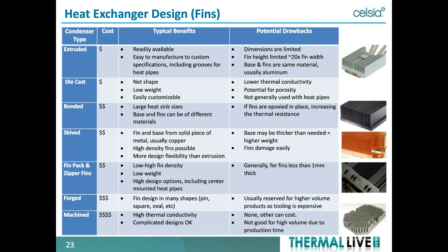The heat exchanger design used for these devices is no different than what's used in just typical heat sinks. You can use extruded heat sinks, die-cast heat sinks. You can use bonded fin, skived fin, fin packs, forged fins, machined heat sinks. I think the most common that are used in the marketplace is probably fin packs because they're used in notebooks, and machined heat sinks that are used in really high-end applications. So the most common ones are the fin packs and the machined, although you can use any of these with heat pipes and vapor chambers.